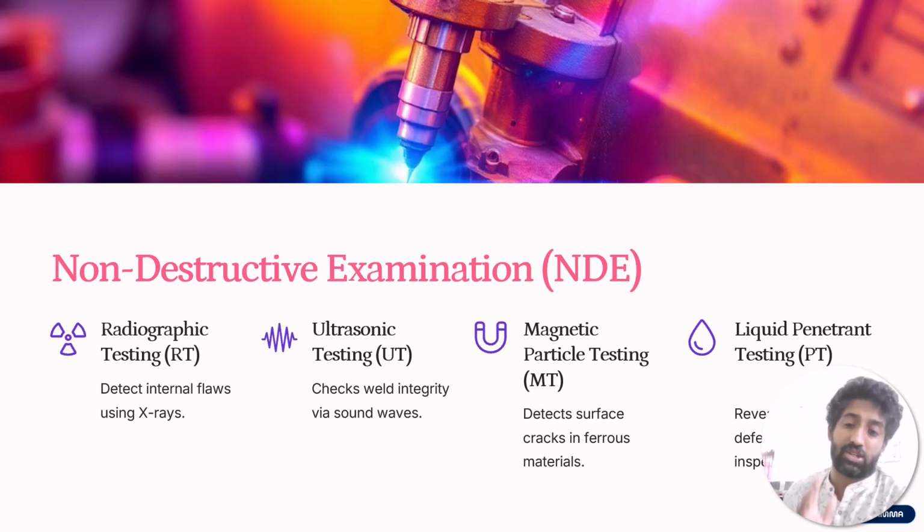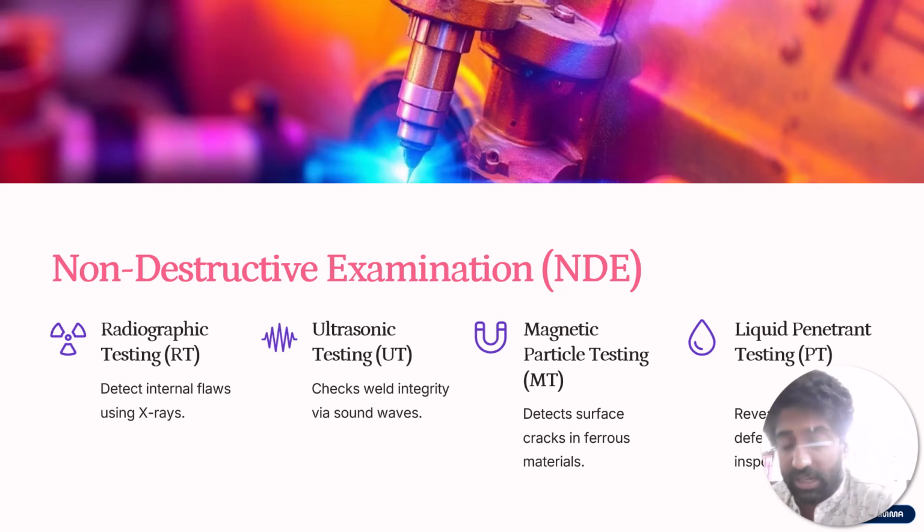If there is an indication in the penetrant zones that the cracks are more, like more than 30% in a zone, which is a basic standard, then that zone or section can be omitted and sent for remanufacturing, starting from the furnace to your machine. That means anything can happen. Okay, next.